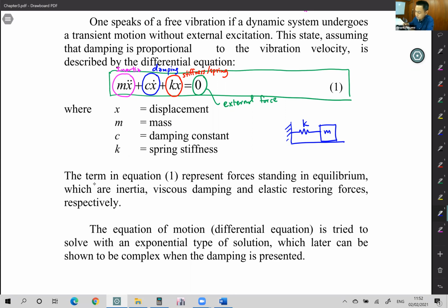It will try to dissipate the energy from your system to the heat of the friction surface. So your energy inside your system will be smaller due to this friction force and stop the vibration. This friction force can be one of the damping forces. Mechanical engineers use a lot of friction damping. Sometimes they call it Coulomb damping.